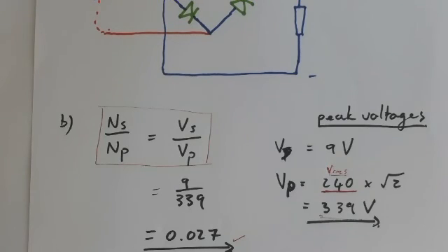So if you look at page 288, they give that formula there where you do 1/√2 times the peak value. That's it, yeah. So then you multiply that by the 9 and then divide it by 240. But I guess that might not be correct in the sense that the 240 volt is the alternating supply. Yes, and your direct current is just this steady one. That's not the one that goes up and down. So it is your alternating one that you need to work with.